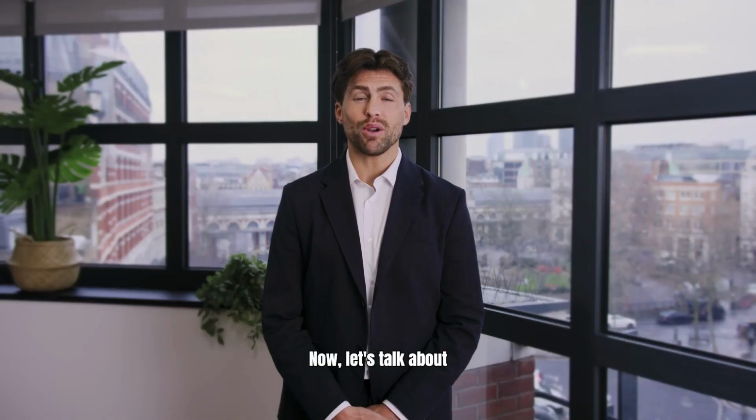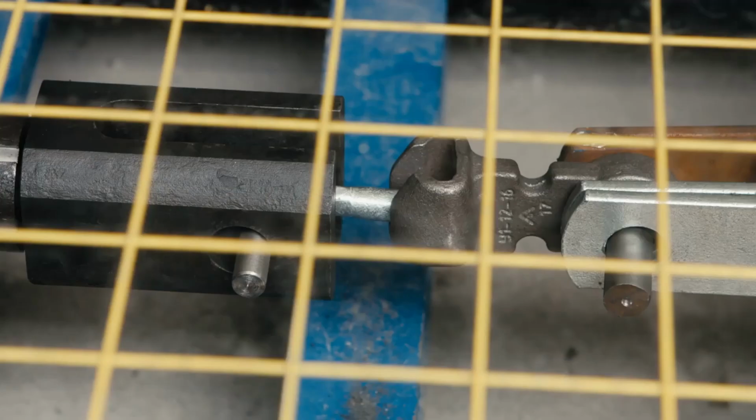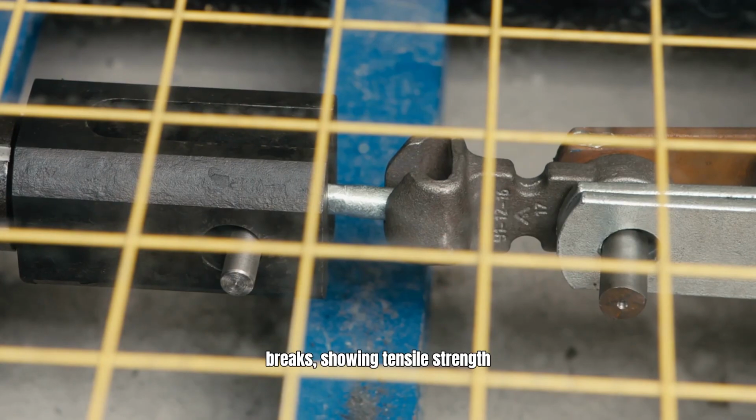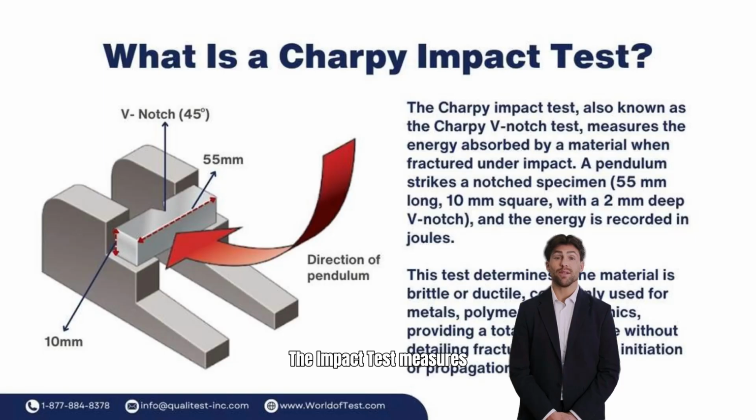Now, let's talk about destructive testing, where the weld is broken to check its real strength. The tensile test pulls the weld until it breaks, showing tensile strength and ductility. The bend test involves bending the weld. If cracks appear, the weld fails. The hardness test checks the heat-affected zone, as too hard means brittle and too soft means weak. The impact test measures toughness, especially important in pressure vessels and structures.